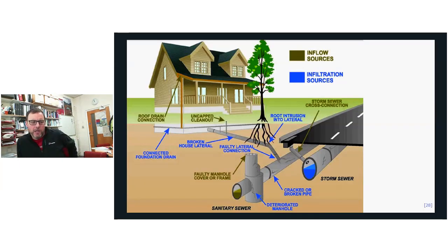Okay, so where you get issues, and it's illustrated to some extent here, is where you have root damage to pipe networks. So as well as aging pipe networks, you have root damage, where the roots find their way in and prise open small gaps. Traffic loading can be a big issue, and if particularly the pipe's near the surface, traffic loading can result in deterioration of the pipe network as well, and also where it's been poorly laid or designed or constructed.